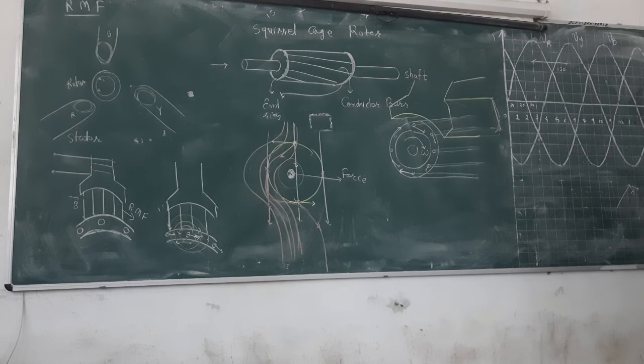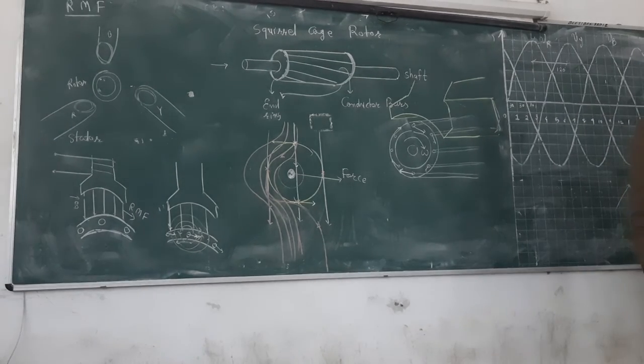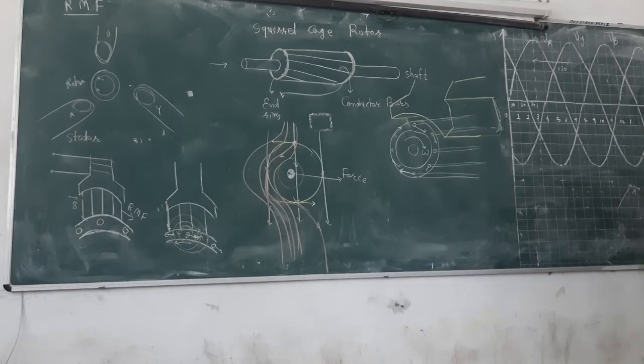In space, if you have a three-phase winding and a rotor, and the rotating magnetic field is at 3000 rpm, your rotor will start to rotate at 3000 rpm. Then both have the same rotating speed, no relative velocity, and no extra electromagnetic induction. Now you do not need three coils. Remove the three coils, and the rotor will rotate forever at 3000 rpm in space. On earth, bearings are there.